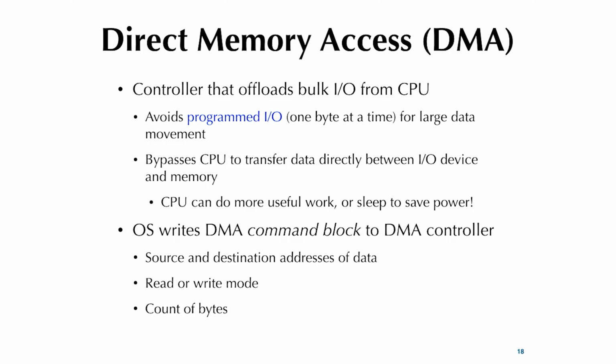Okay, so now DMA, you may have heard of several times. That's direct memory access. That is where you want a controller to offload a lot of what's called bulk I/O. So what does that mean? With, say, the serial port or UART, you're actually doing what's called character I/O, writing a byte and reading a byte. That's 1 byte at a time. Yeah, the processor can deal with that.